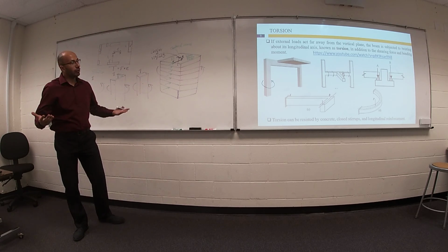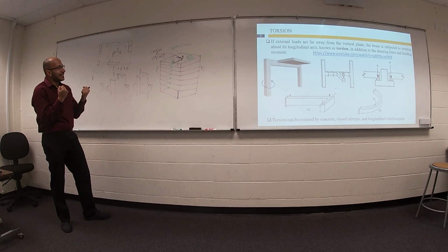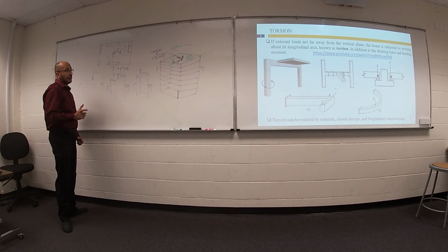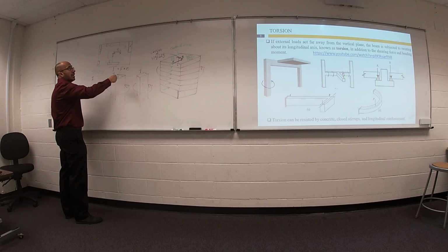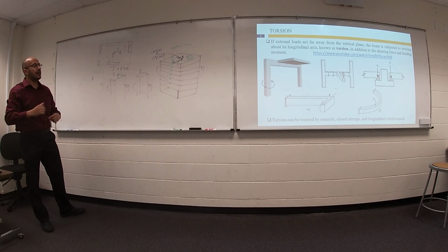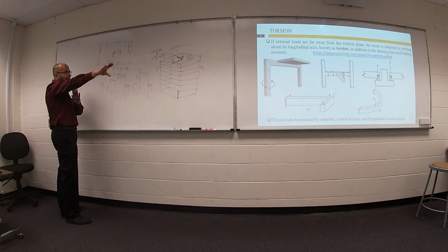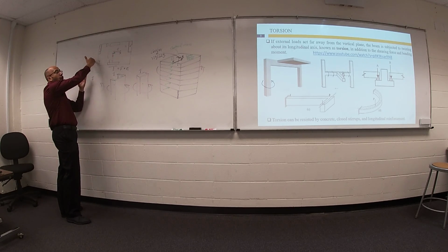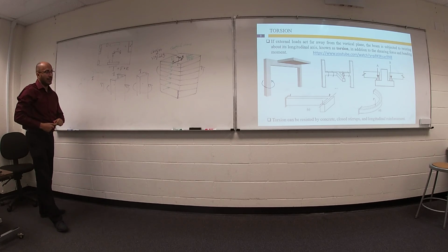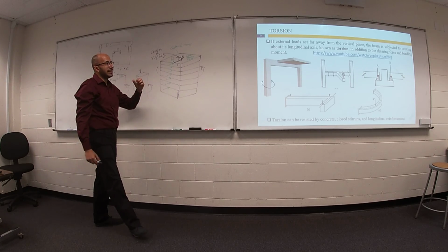So I have some limitations on your distribution, but as a structural engineer, be careful. If you put a strong, meaning big, column on one side, maybe at the edge, you have to put another one, or maybe two, equivalent to the strongest one to make your center of rigidity in between.